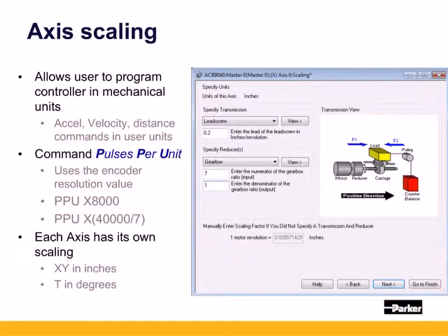With the ACR demo with the BE motors with the J encoder, those are 8,000 counts post quadrature. If you wanted to program in revolutions, if you set the transmission type to none, it would then set PPU to 8,000 if you query that in the terminal window with PPU space X. If you had a 5 rev per inch ball screw and a 7 to 1 reducer with a J encoder, this would be 5 times 8,000, which is 40,000 counts divided by 7.